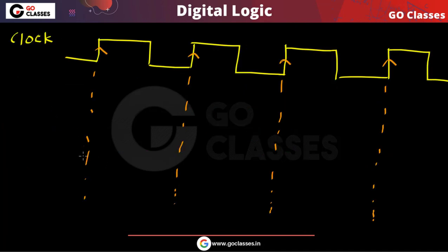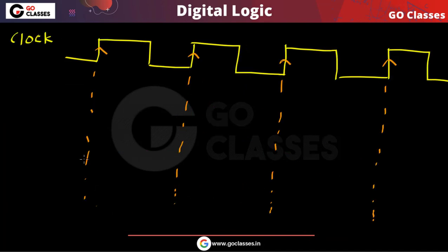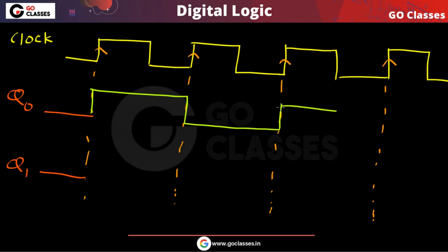Let's assume this is the clock. You already know that when the clock goes from 0 to 1, making the rising edge, q0 will toggle, and this q0 is the clock for the next flip flop. So when q0 goes from 0 to 1, q1 will toggle. Let's assume initially q0, q1 are both 0, 0. With every rising edge of the clock, q0 will toggle. So this is your q0.